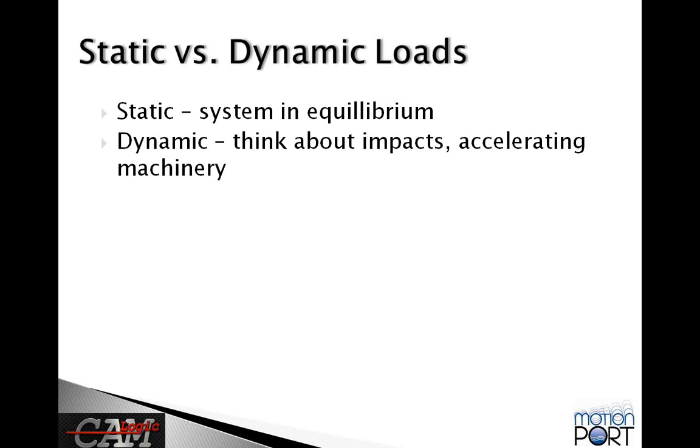And so some characteristics of dynamic loads have to do with the system having an impact occurring, or there might be acceleration in the machinery, or even just steady rotational velocity, but maybe an imbalance of what's being rotated, that can cause some kind of a pulsing load according to the rotational speed of the system. So when you think about dynamic loads, there's going to be some kind of motion involved in the system, and